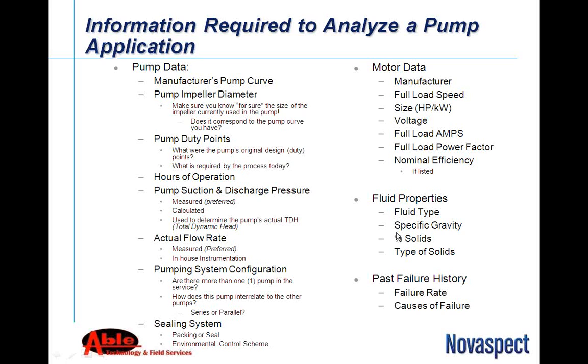Fluid properties. You're going to need fluid type, specific gravity, percent of solids, type of solids. This all has a lot to do with the life of your pump when you put this all together, so it's going to be very important.